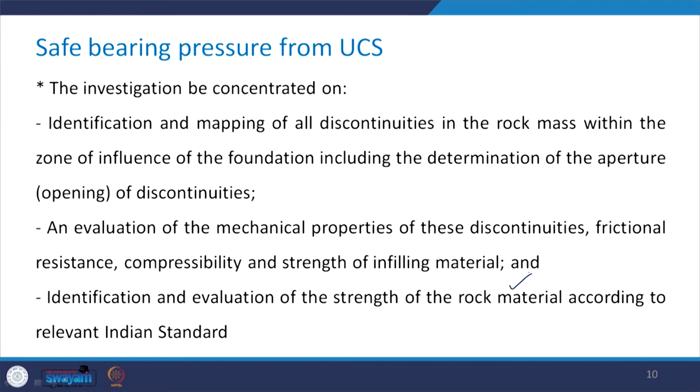An evaluation of the mechanical properties of these discontinuities, frictional resistance, compressibility and strength of the infilling material, if any. Let us say if the joints are open and if there is any infilling material in between, all these factors influence the safe bearing pressure and therefore these should be evaluated properly. Then the identification and evaluation of the strength of the rock material according to the relevant Indian Standard Code should also be done.